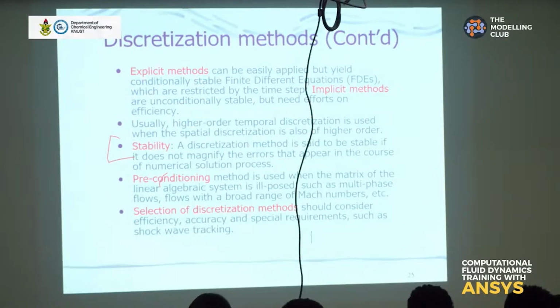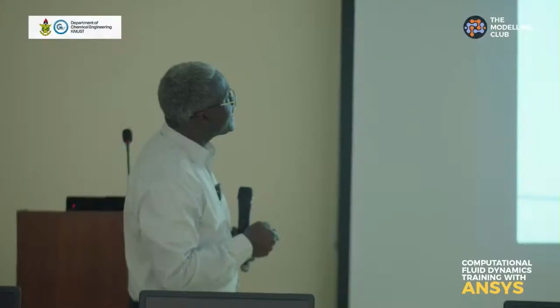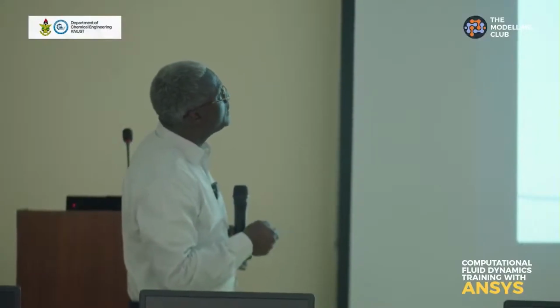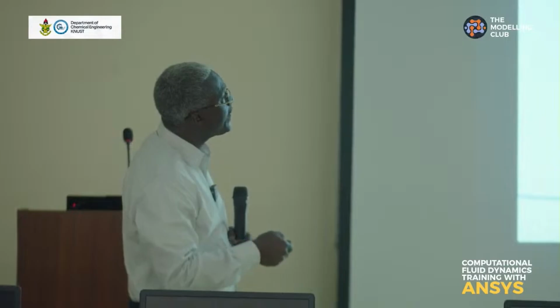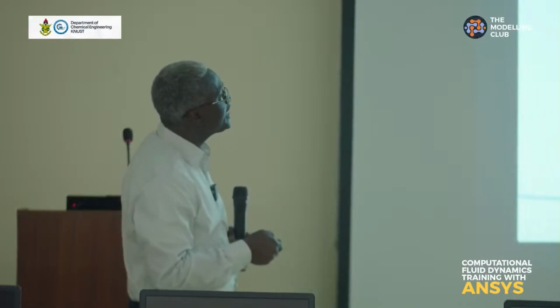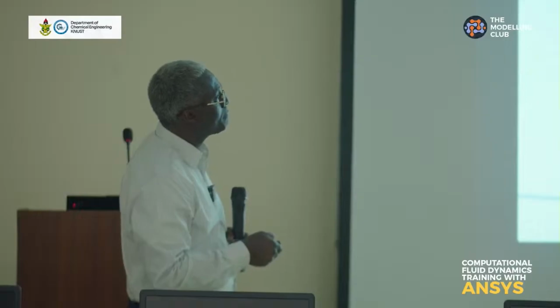Now, if you are discretizing using an explicit method, we are saying that explicit methods can be easily applied but yield conditionally stable finite difference equations, which are restricted by time steps.